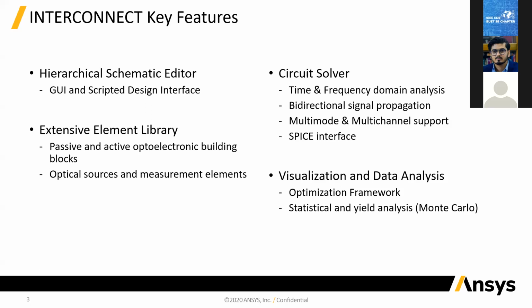The statistical analysis part is pretty critical when you're doing a circuit simulation, just because when you're going into circuit simulation, you have so many components in your design, and as you fabricate them, you can imagine that there's always some variation coming from the fabrication process.